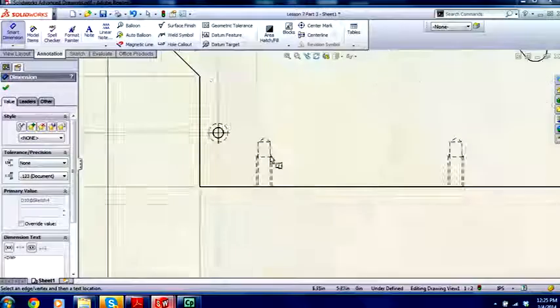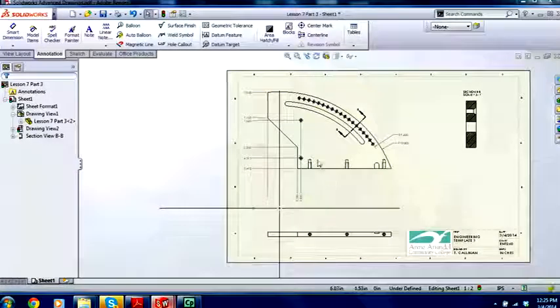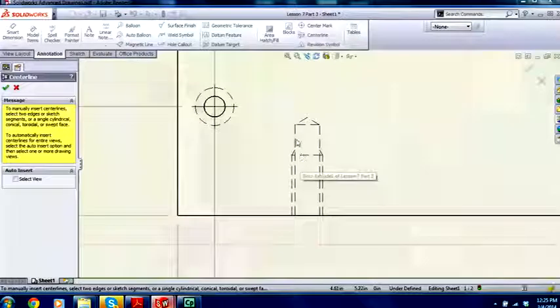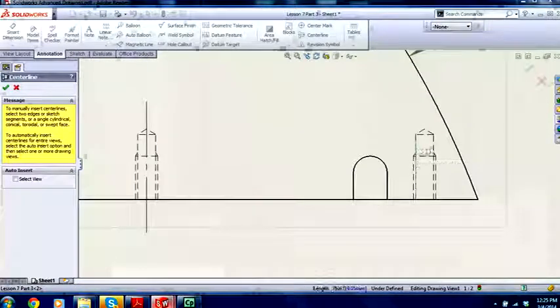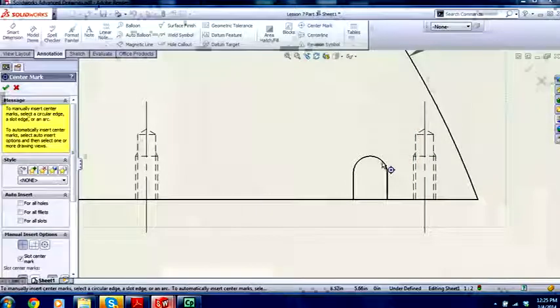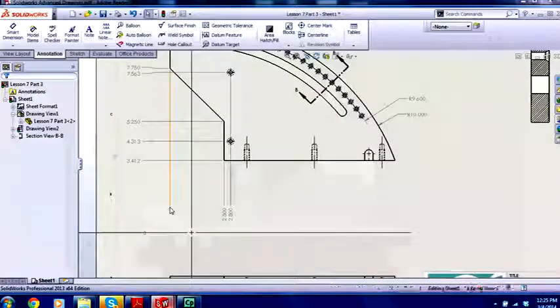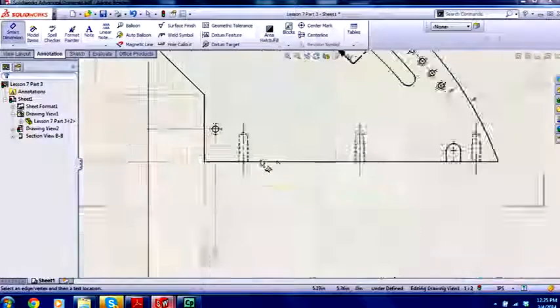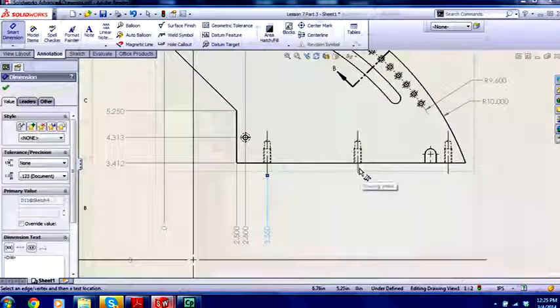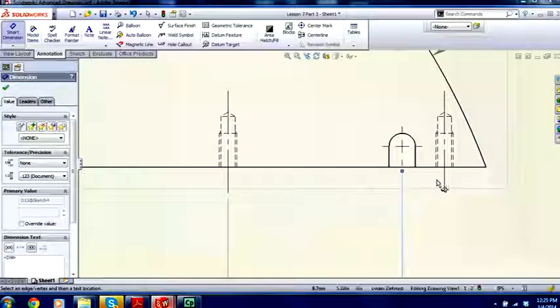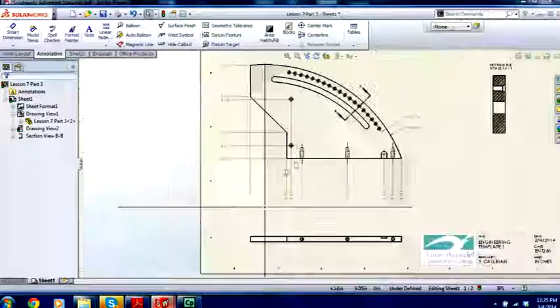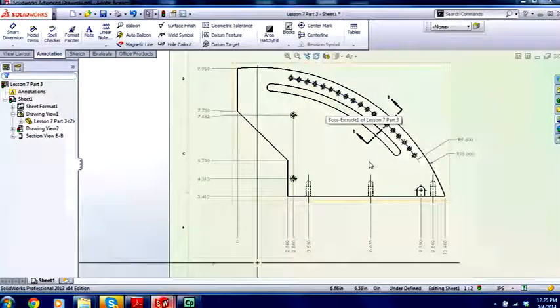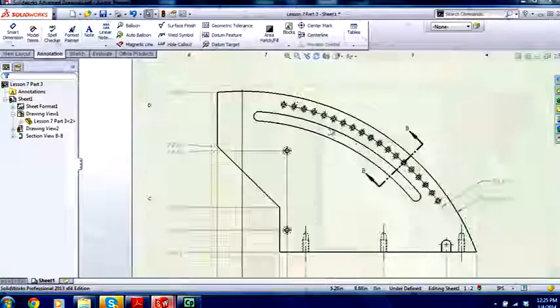3. Before I can put these in, I really need center lines. So just let's hold on for a sec. Let's go center line and click on 1, 2 edges. Like so. And let's put a center mark in here so we have that. And then let's right click and go add to ordinate. Can I keep on going? Lovely. So I'm after telling you don't do ordinate dimensions, but for something like this they're much easier. This is quite complicated.